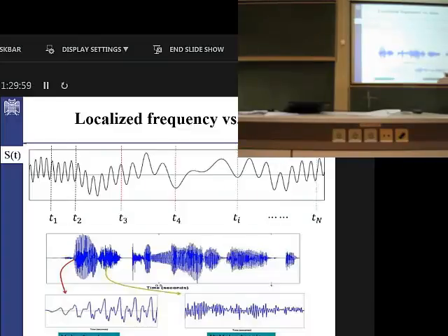So if you take this window to be from the beginning to the end, there is a frequency component that appears that will never appear if you just look at every single window. And that's the frequency of the signal over the entire envelope.